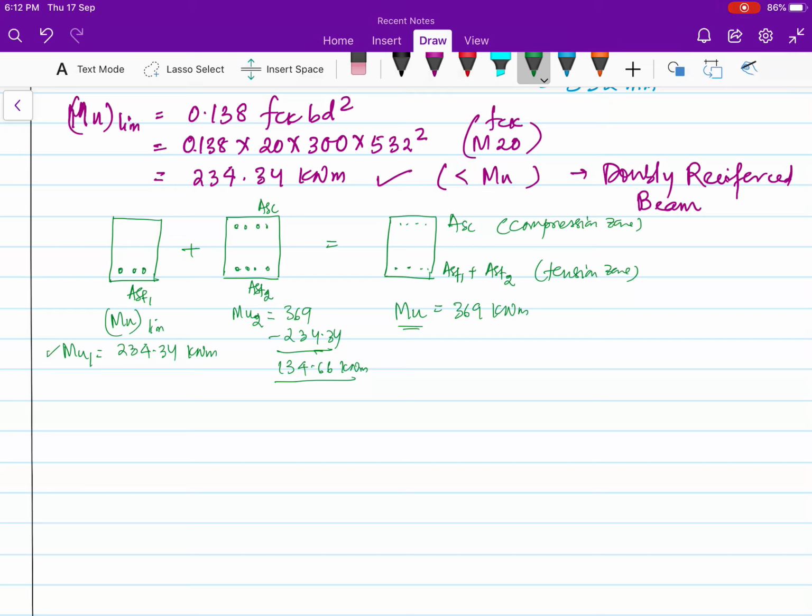So this case is like your singly reinforced. If your limit would have been less than this, directly you could have designed for as singly reinforced. So let me put Mu1 is equal to 0.87 Fy into area of steel 1, into D minus 0.42 XU.